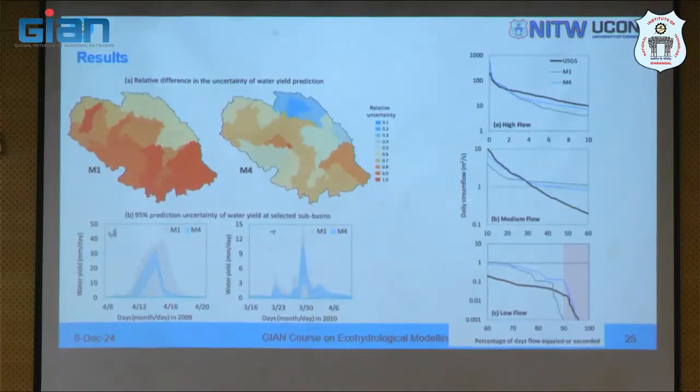This is something which was fascinating, and this is something which we also tried for the ungauged basins. We have not tried with the SWAT model, but we used a conceptual model GR4J to see if we can predict, or estimate, the parameters using soil moisture data alone. One of the studies which Pattabhiraman had done while being here took different catchments, and this was basically an ungauged study. You have the ungauged catchments, and to estimate the parameters of ungauged catchments, one of the ways was the regionalization approach.